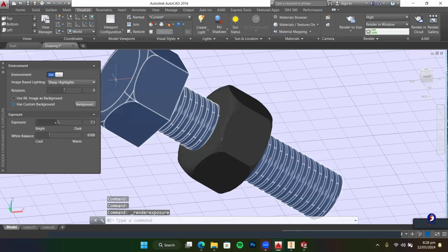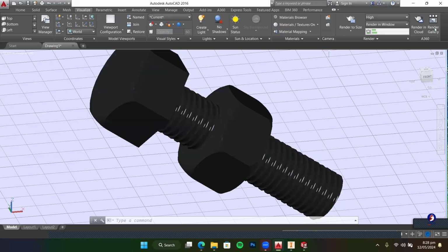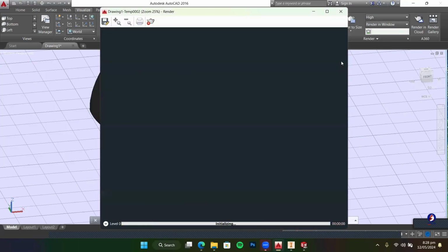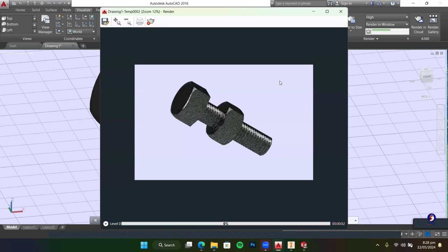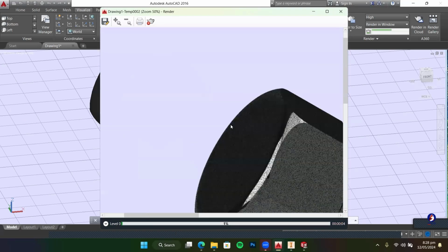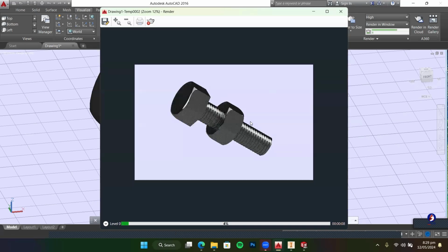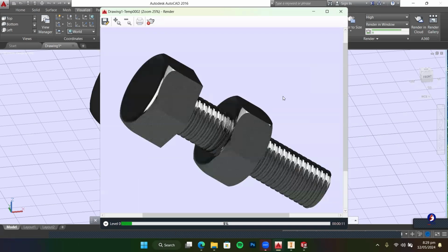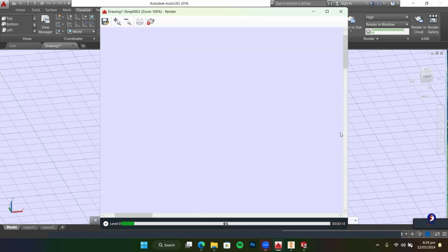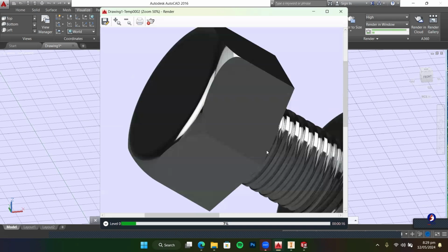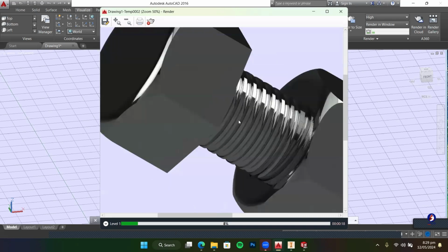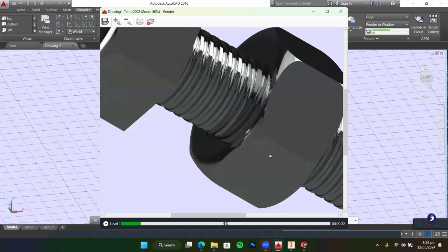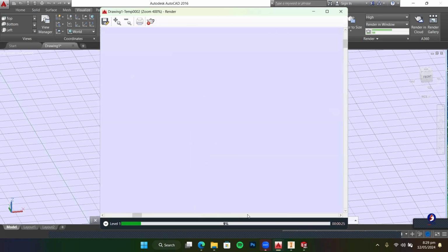So I'll just adjust the exposure. I have my standard exposure I use, which I've used in so many drawings. That's 8.5. That's my standard exposure I use personally, 8.5. I'll select render again. Now I think the tone is okay. I think the tone is okay now. You see, the more the bar loads, the more the pixel changes.